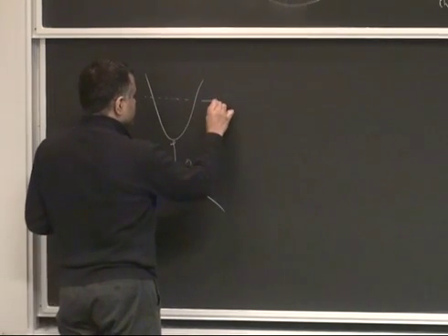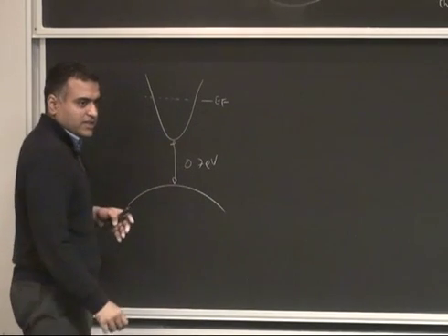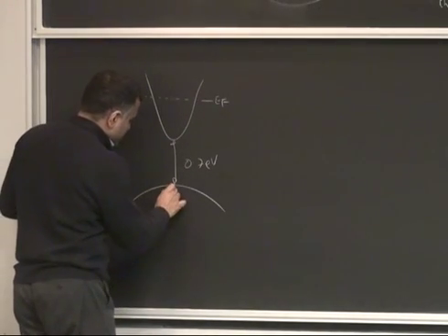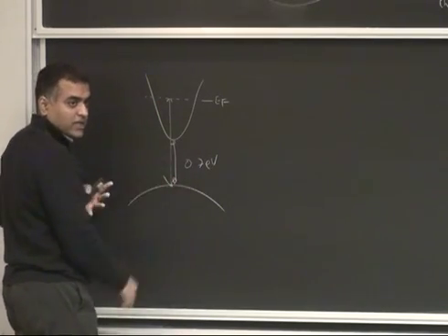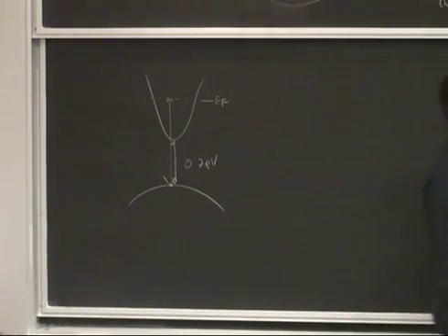But it was so defective, and it was highly n-type. So the Fermi level used to be very deep in the conduction band. And then when you do an absorption edge measurement, your excitation edge is kind of this much. It's not the band gap, so you get a blue shift called a Moss-Burstein shift and all that. Anyway, end result,